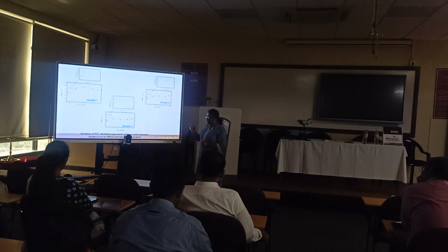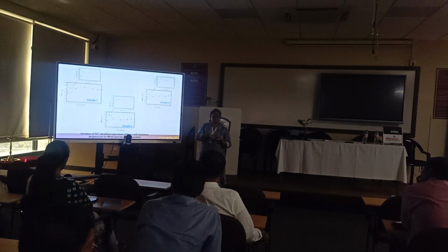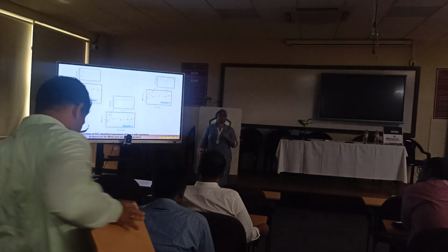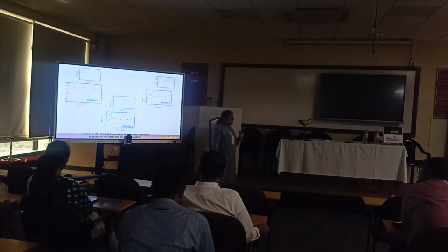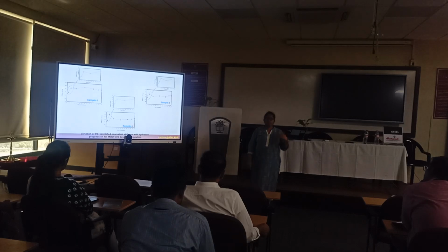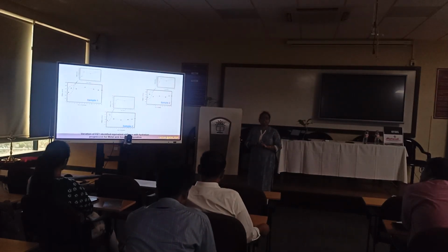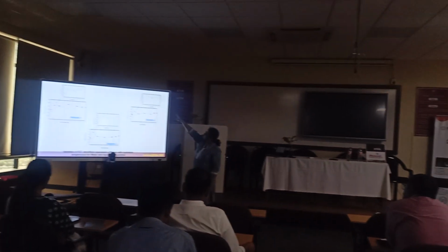But I simply wanted to say here, the stiffness measured through the Gibson model is plotted over the 20 days of hydration, either in a short form, that is from 1 to 14 hours, that is the 2 days of hydration for short term, or long term hydration, the change is happening. Looking at the behavior, why should I talk about concrete, corresponding to how it is hydrated: we just said through solution hydration, and there is a solid state hydration. Now the first 3 days are very much responsible for early strength and high heat of hydration as well as setting time. So you see there is a large increase of the stiffness values.